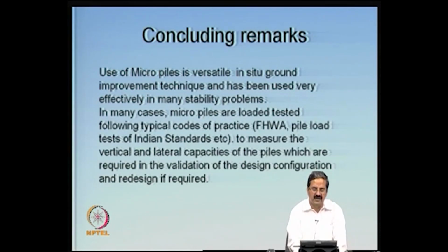Actually, that is a little bit of loose dumped material, and normally the tendency is that if you want to calculate the foundation sizes, you must assume some bearing capacity and come out with the widths of the foundation and other things, the area of the foundation that can distribute the load. But if the bearing capacity is going to be low, then you need larger areas.